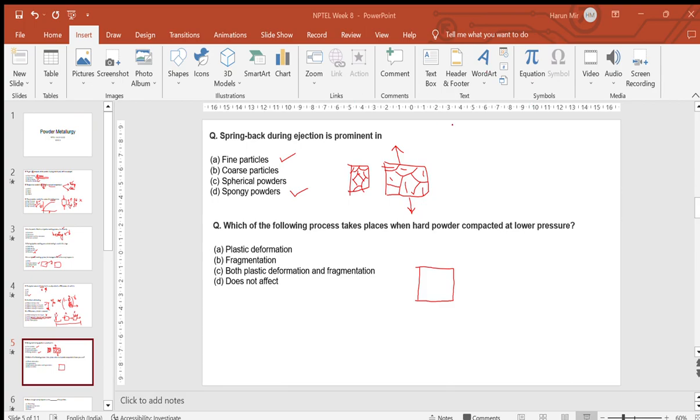If you know the mold that we have, it is porous. So all the water binding material, because there is also water being used in these types of binders. As a binder, apart from the organic material, water is also used. So that water needs to be removed from the mold or compact. So we have porous molds, which allow the percolation of water, and it is also carried out with the help of capillary action. The water preferentially moves through those capillaries and thus results in the drying of the mold. So porous and capillary is the right option.